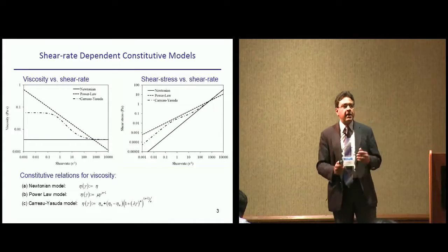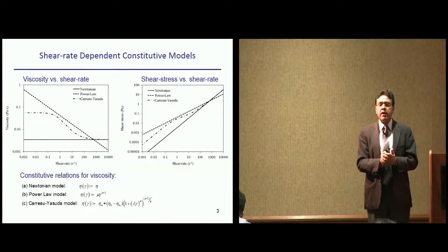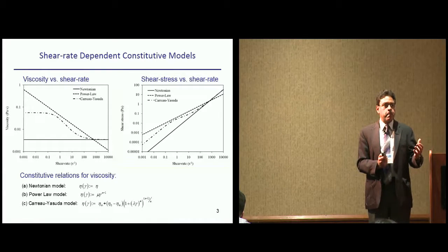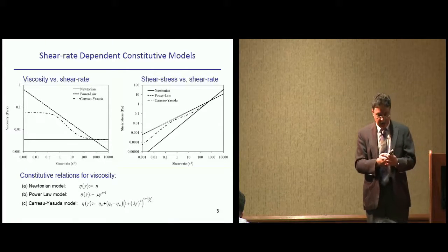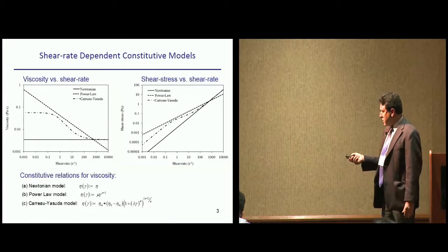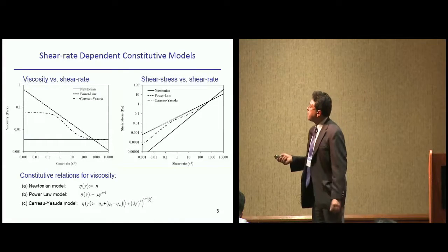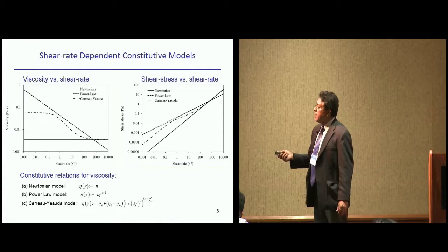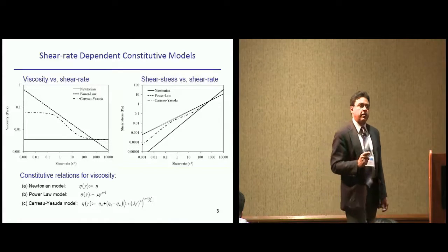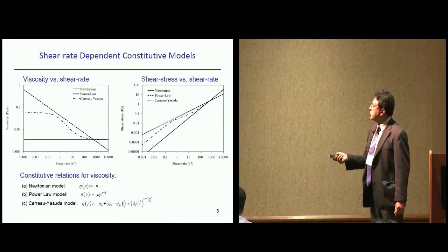And as I mentioned, blood has a tendency to coagulate. If you don't shake it well, if it is not shaken, its viscosity increases. Lucky for us, the heartbeat gives a stop-and-go type of motion, so a lot of shaking. Because of that, its viscosity decreases, and so we don't have the issues. However, most of the time we are in this range, so our shear rate goes up and down, and viscosity varies considerably. This can be contrasted with typical fluids, air or water or oil, where viscosity is assumed to be a constant.